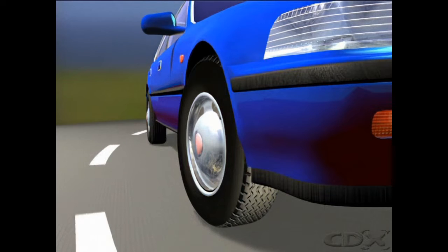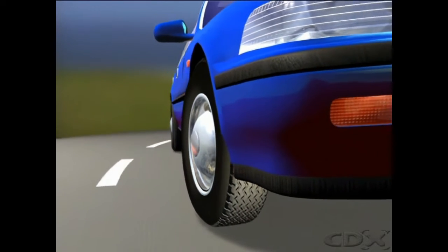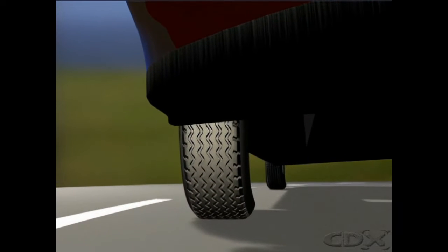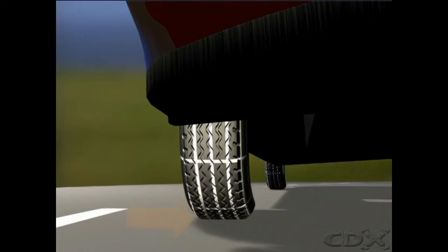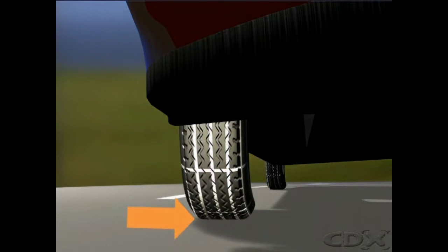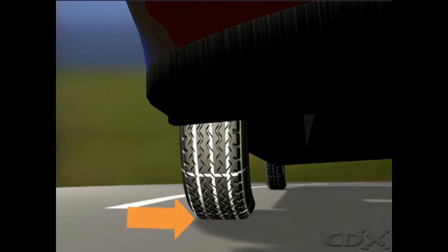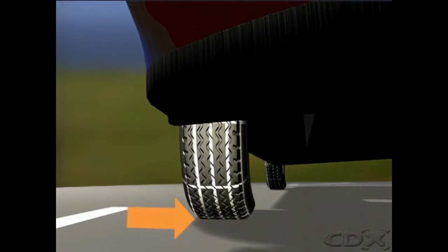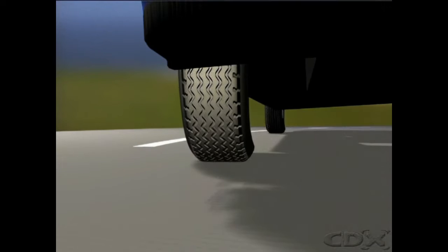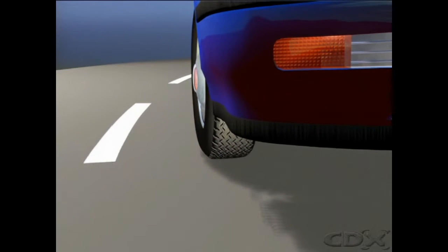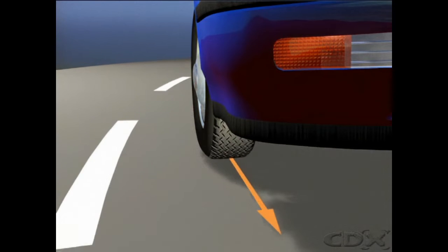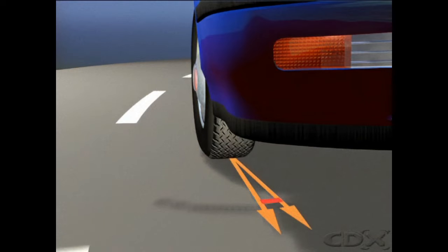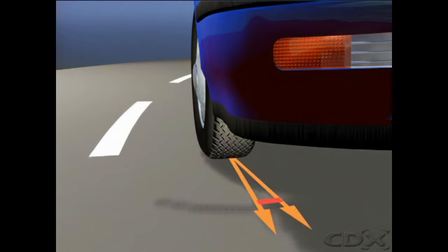The pneumatic tire provides this opposing force by being able to distort while still gripping the road. Then, since the tire's construction makes it elastic, it exerts a force called cornering force, which acts between the tread and the road surface. It pulls the distorted rubber back to its normal position. The tire's sideways distortion makes the vehicle follow a path at an angle to the direction the road wheel is pointing. This is called the slip angle. As cornering force increases, so does slip angle.